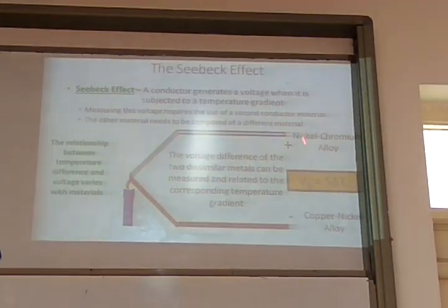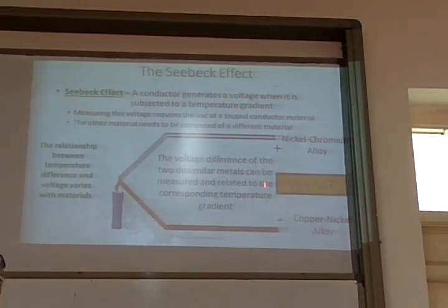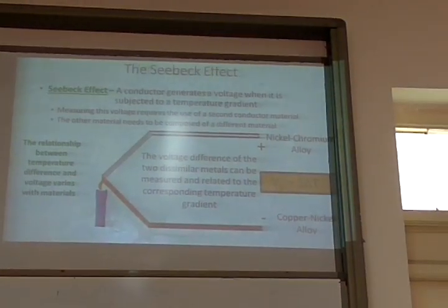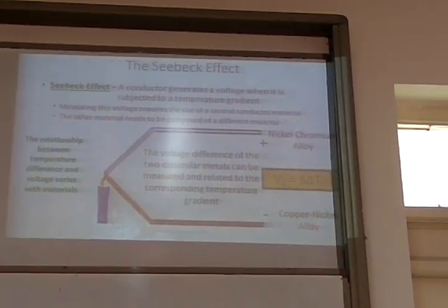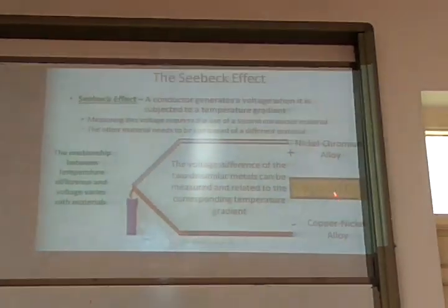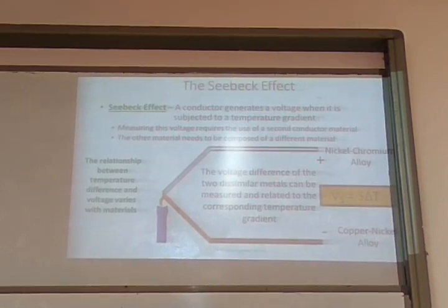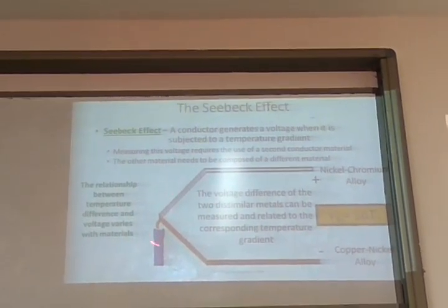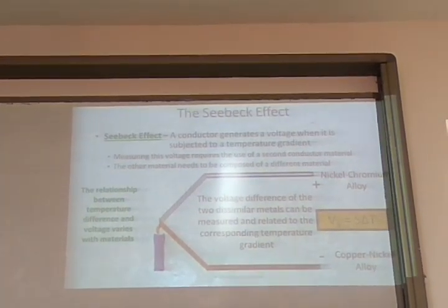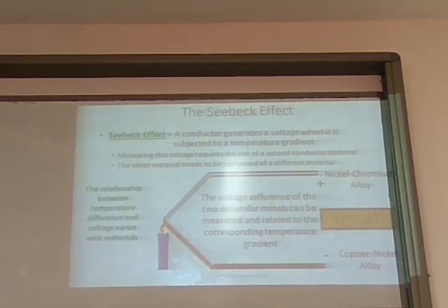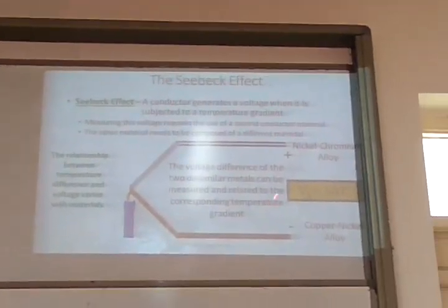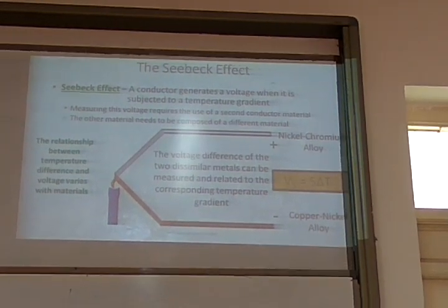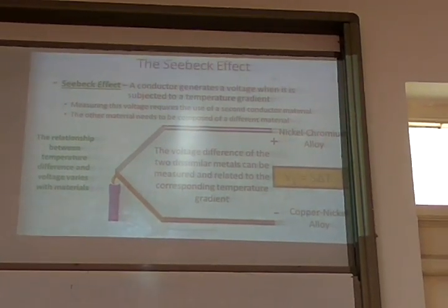Now, the thermoelectric voltage or thermoelectric EMF. EMF and voltage are more or less the same, so we use them synonymously. The thermoelectric EMF that is generated is proportional to the temperature difference between the cold junction and the hot junction. The temperature difference between hot junction and cold junction is delta T. Proportional to that, the voltage is generated. That's the thermoelectric voltage. Up to this is clear.